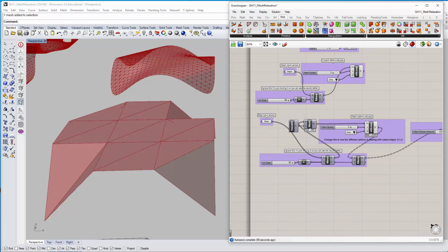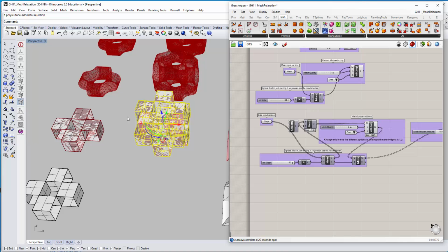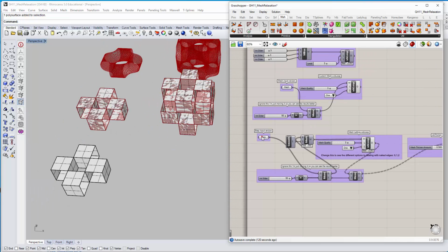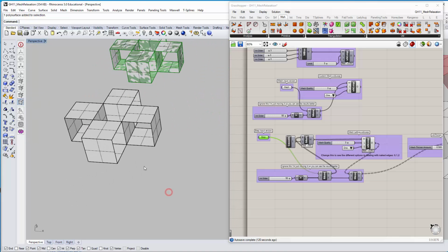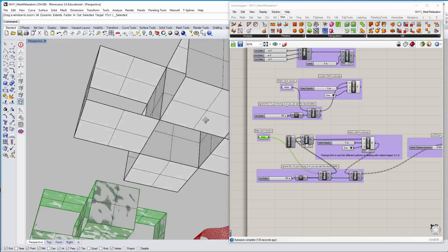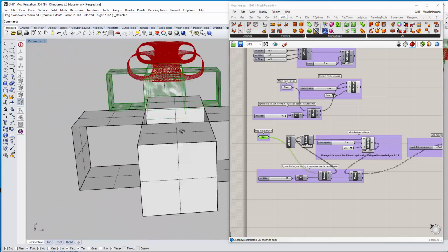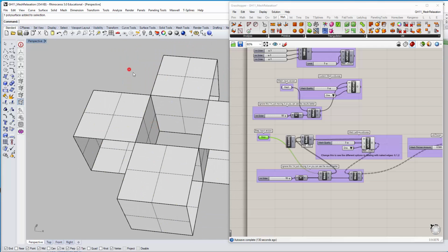Now the last example we're going to look at here is a version of this. So obviously you can see that you can actually draw your own, let's say, mesh planes or mesh topology structures to kind of work with, in this case in particular, the Weaverbird loop subdivision method. This one, as you can see, is actually, and I've linked both of these in a simple and a complex version. The simple version is just this, right? It's actually a series of these interconnected boxes with some faces deleted out as a whole poly surface.